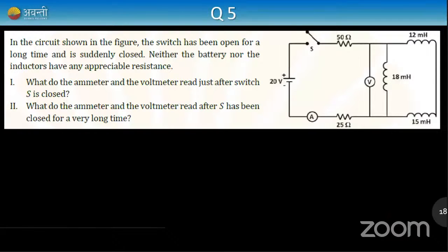So take this as homework, try to solve this question. Here also I'll give you the same idea. There's a very complicated circuit here, but let me tell you, this has a very simple solution. At time t is equal to 0, what will happen to the circuit? At time t is equal to 0, the inductor will block all the current, right? So I have to remove the inductor. You have to remove this wire, this wire, and this wire. Now the circuit is incomplete.